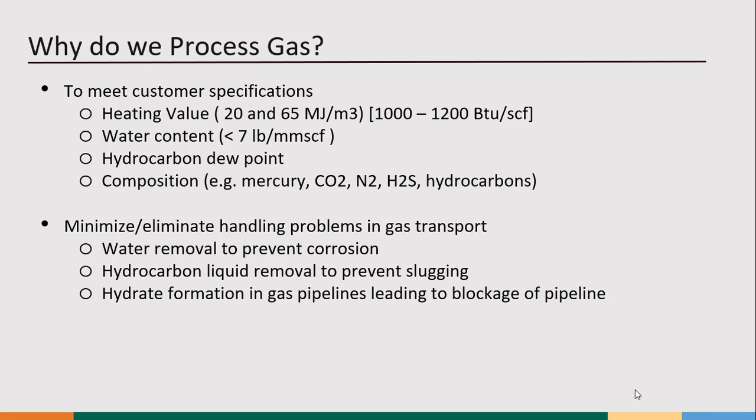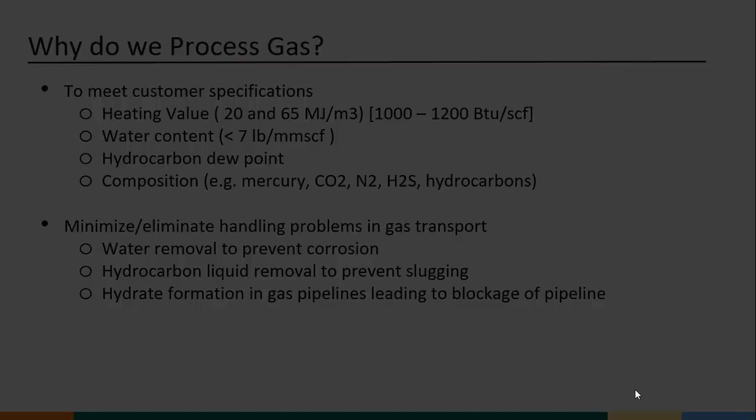And third is hydrate formation in the gas pipeline, because hydrate is not just the presence of water. We will discuss it in detail. Hydrate formation in a gas pipeline can lead to blockages, complete blockage of the pipeline. We will see how this works.